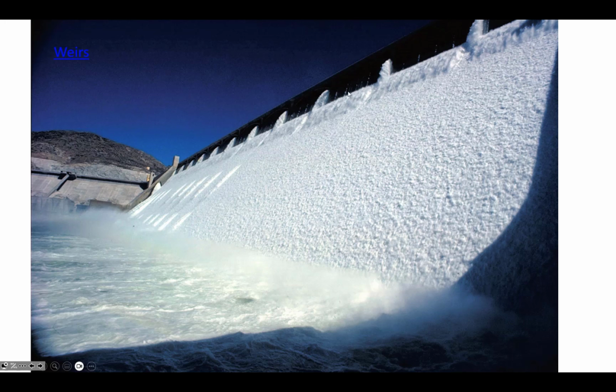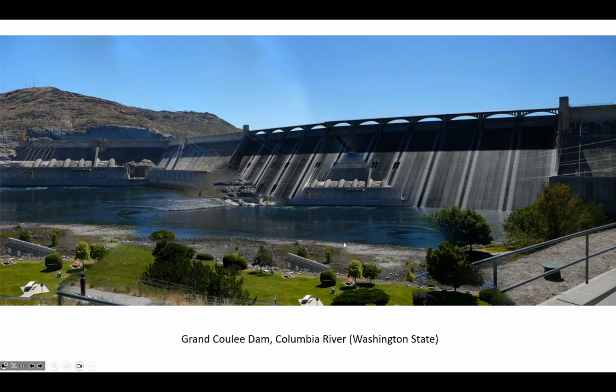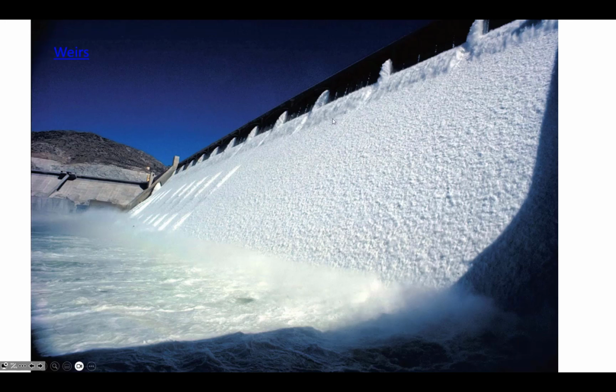But the slope of these spillways is designed to help dissipate energy, because the river downstream could be really badly damaged and scoured if the water, which is falling hundreds of feet and picking up a lot of energy as it falls, is just left to flow at a high velocity. And so they're intentionally designing these spillways to cause a hydraulic jump downstream and control the location where that energy is released, rather than having a high velocity and scour potential downstream.